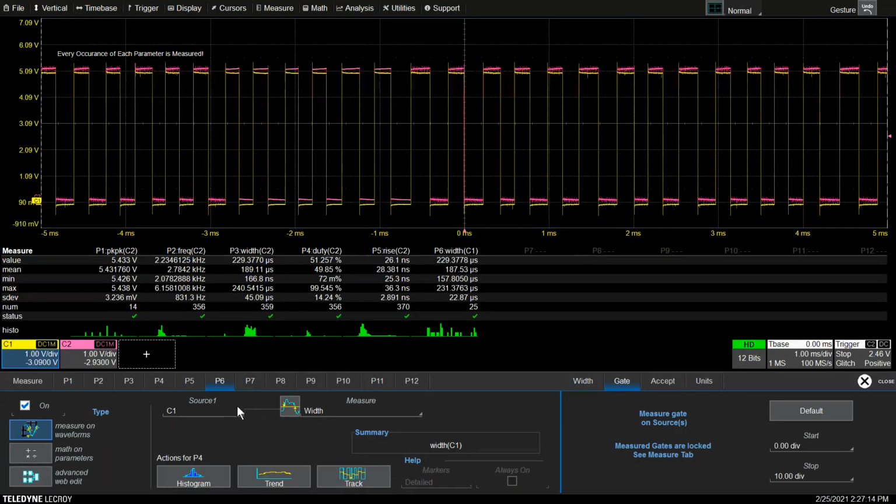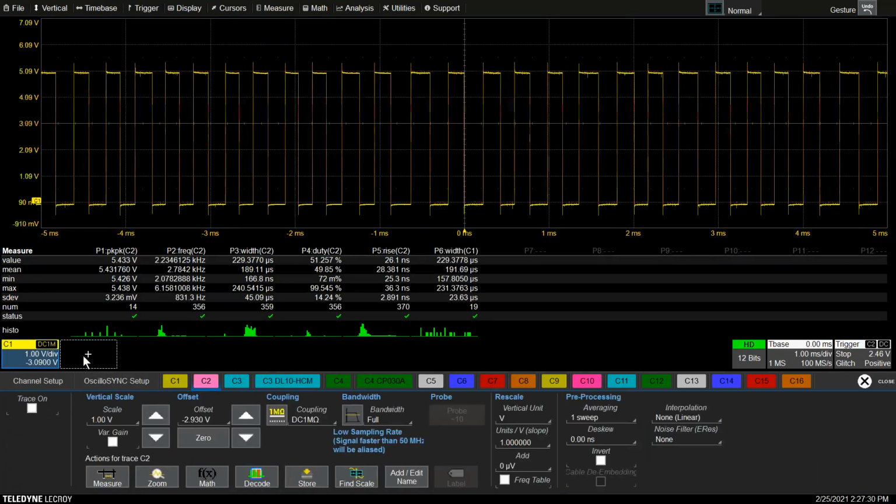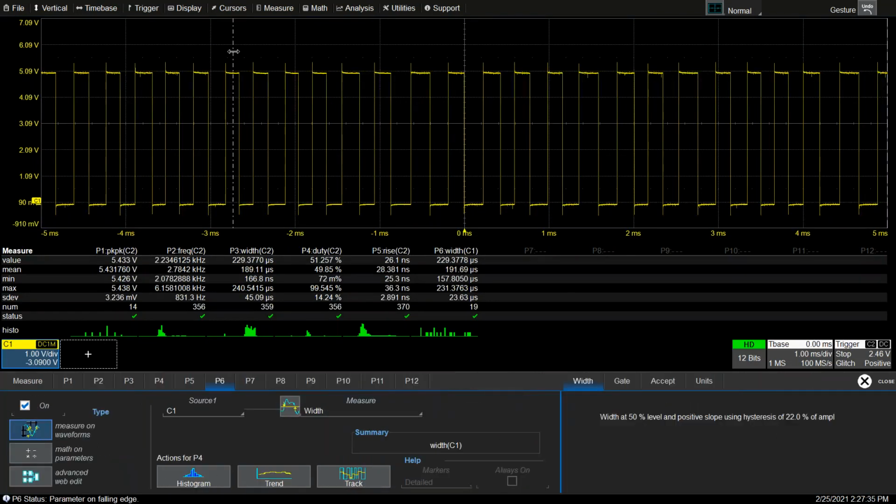Here, off to the left on this particular oscilloscope, it shows you the source and the measurement selected, but on the right is gates. And don't forget, when you look at your gate, look off to the left here. And let's simply shut off 2 at the moment. Okay, since I picked on this, this is one gating cursor. Gating measurement, I can move this over, yeah, and then here off to the right is the other. So now the table has been duplicated and the measurement is duplicated, the source is now channel 1, and I also have the gates turned on.